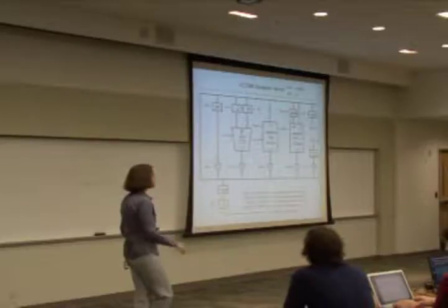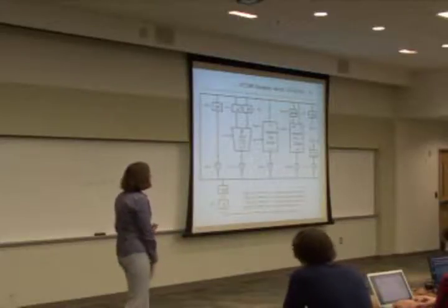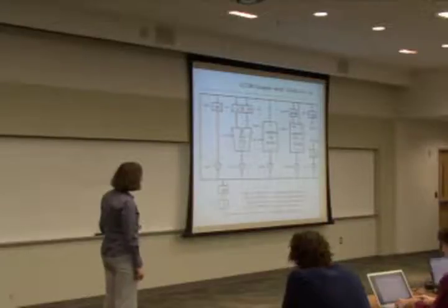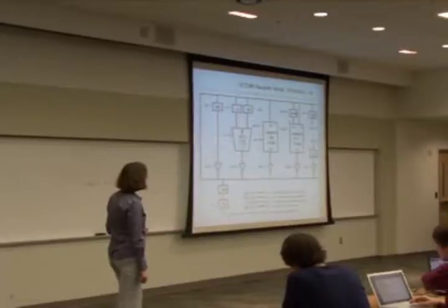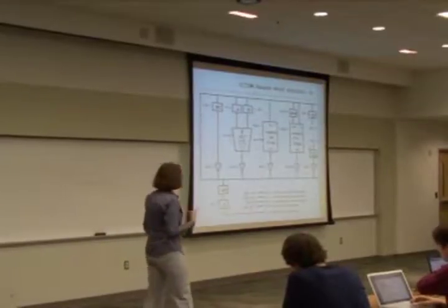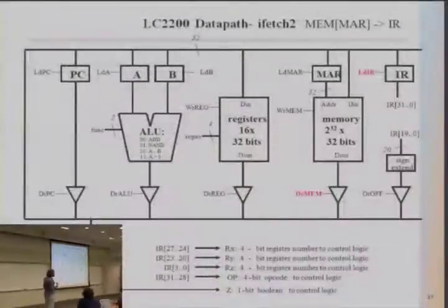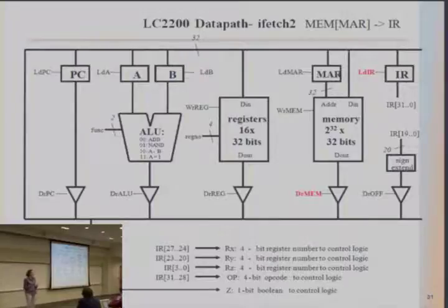That's the whole concept. Okay, so now that we have the address in memory, we access that and read it. To let it out on the bus, we need to set drive memory to 1. And now we have, again, 32 bits traveling around, and the instruction register reads them. So in this step, basically, this instruction written as zeros and ones is loaded in the instruction register. Okay?